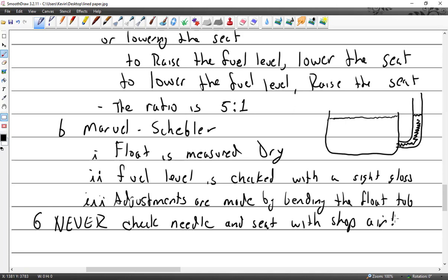So it's air, spark, fuel. Does it sound like it's running out of fuel possibly? Yeah. Okay, it's either running out of fuel or running out of air, or suddenly the spark is quitting for some unknown reason, which doesn't make sense. Or mechanical. Mechanical would be something like you mistimed the internal of the engine, you have a stuck valve, something like that. So, basic troubleshooting, it always comes down to those four things. So, you know, we're targeting in on, okay, it's a fresh overhaul.